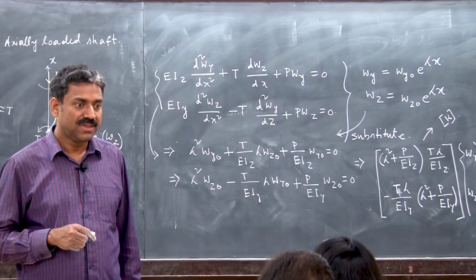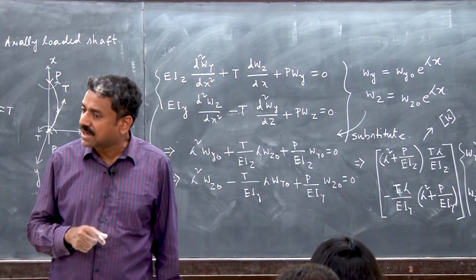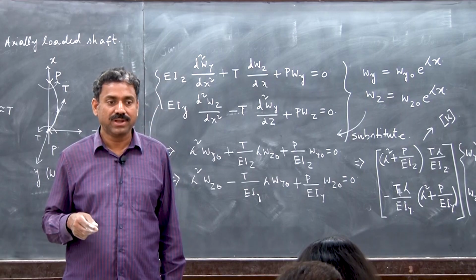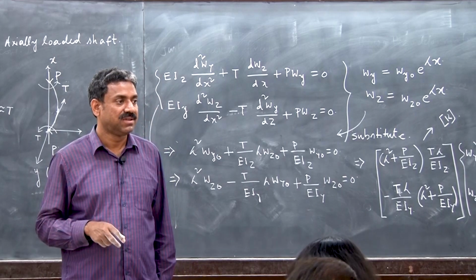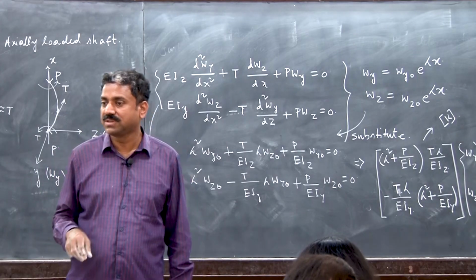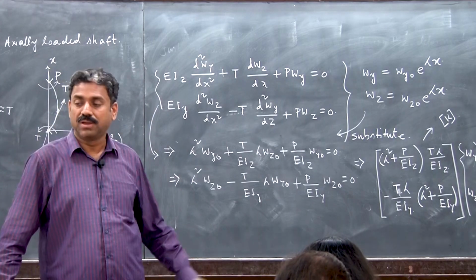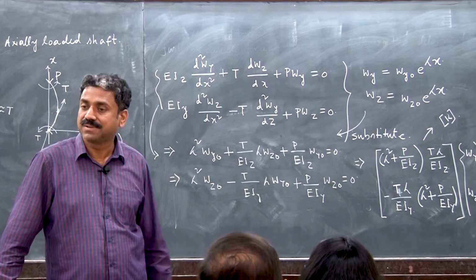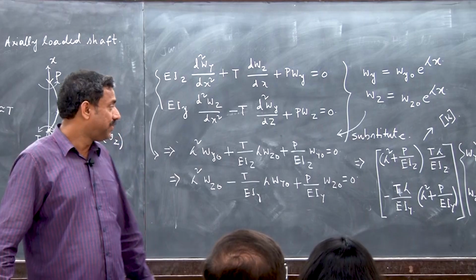This also occurs when a 3D continuum is subjected to damage. In damage mechanics, you will see that because of damage, it sometimes loses its symmetry. Another case in an elastic system is the non-conservative one. So this is an asymmetric stiffness matrix.